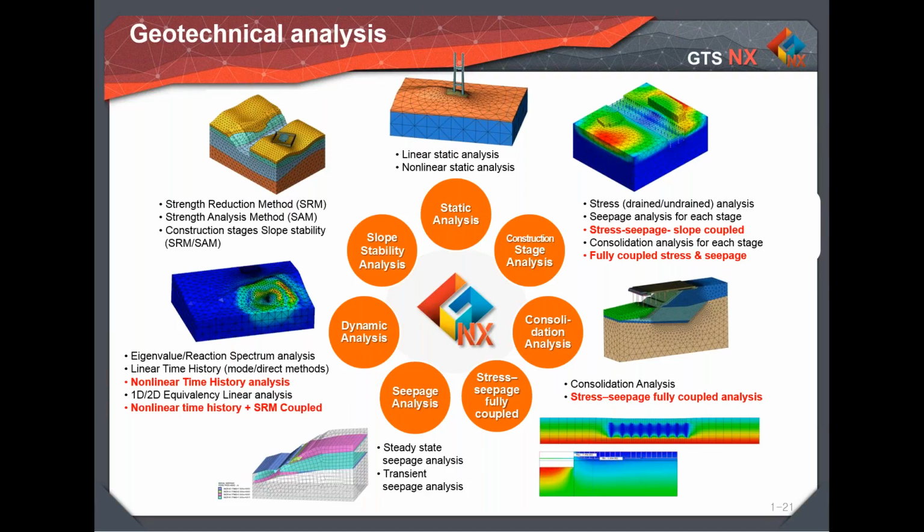What happens is, for example, you are performing a time history analysis, let's suppose due to an earthquake, and you want to see the stability of the embankment or the dam which you have designed against slope failure. You run the time history analysis, and at any point of time you can ask the program to check the slope stability. For example, if the earthquake duration is 6 seconds and you want to check the factor of safety at 3 seconds, it can be checked using the C-phi reduction method. Please note that here we are not applying the load as a pseudo-static force. It's a completely dynamic analysis considering nonlinear time history.